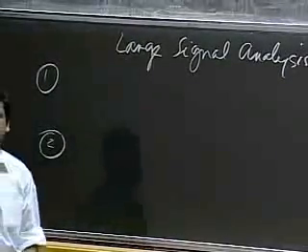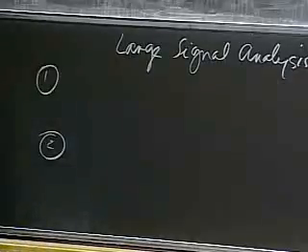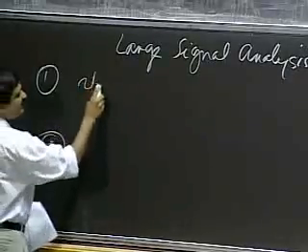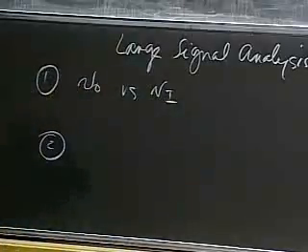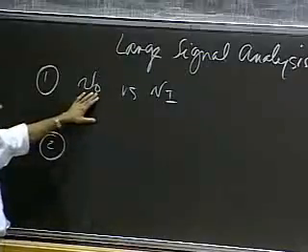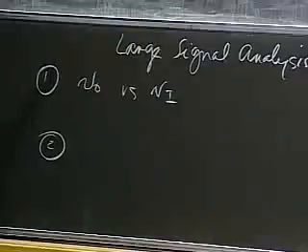involves writing down the transfer function of your little circuit. So in our case, V naught is the output, Vi is the input. So it involves writing down V naught versus Vi. Okay, simply write down the transfer function. In other words, the relationship between the output and the input for that circuit. And in our case, again, we've disciplined ourselves to adhere to the saturation discipline.